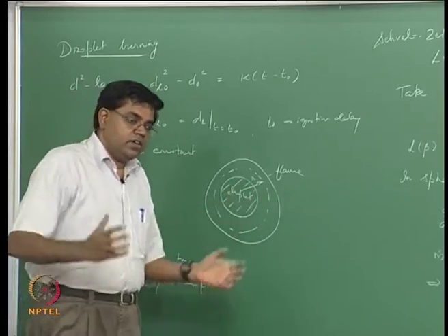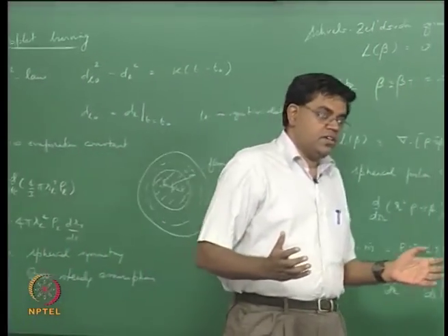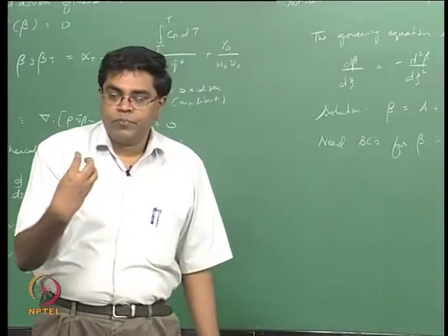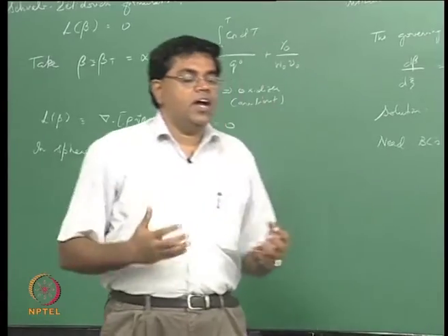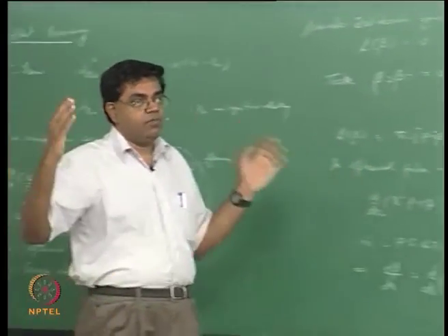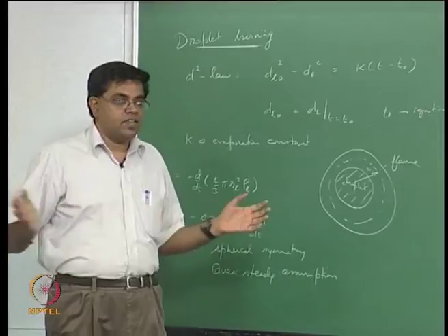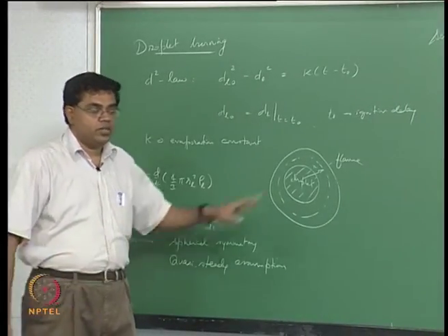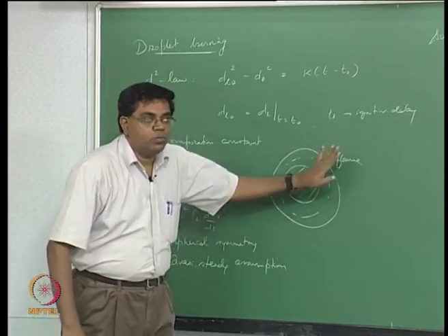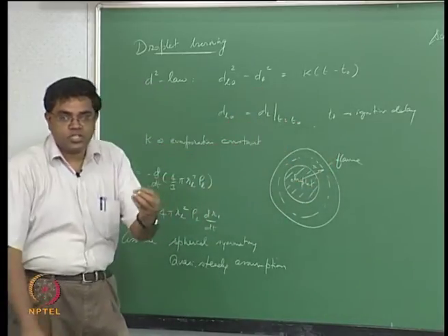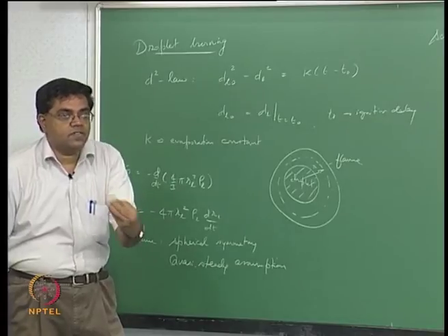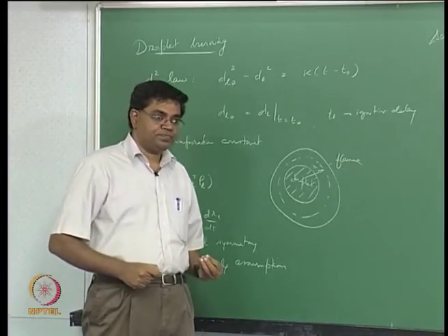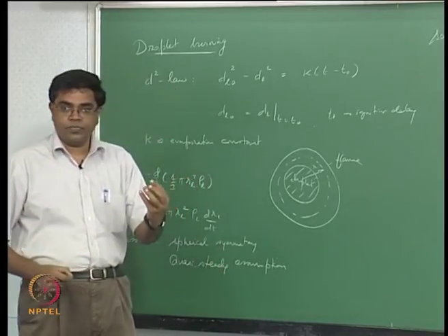As the combustion continues to progress, you get to a point where you are less and less rich in methanol, so what the flame is trying to do is not only vaporize the methanol but also vaporize the water that is mixed with it. Beyond a point it is not getting enough methanol to burn, and so the flame is going to extinguish at a certain size of the droplet, leaving a certain amount of methanol as a residue along with water, right.